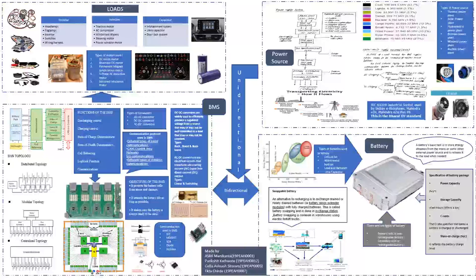Again, the gel battery is there. The gel battery has some scope in the future. Generally, it is a lead acid battery with a jellified electrolyte, in which the sulfuric acid is mixed with fume silica, which gives a gel-like, immobile electrolyte. So this is the gel battery.